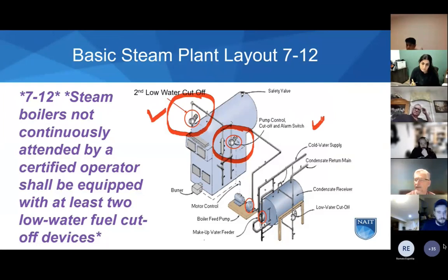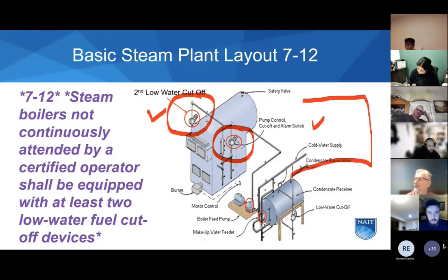Steam systems create steam. If it's a heating plant, it's sending steam out to convectors and radiators and unit heaters with steam exchangers. We're going to condense that steam back to water to take that latent heat out of it and heat up our spaces, our buildings, our processes, our equipment. And then what's called condensate is going to return or come back. So we're going to have some kind of a condensate receiver. We'll look at these condensate systems as we go through these chapters.